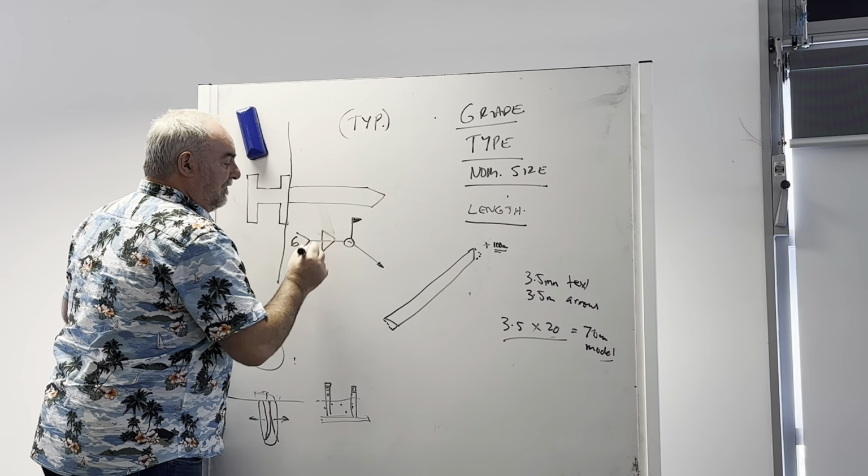Sorry, are we told what the size of the base plate is? No, you've got to make that up yourself. There's a couple of dimensions there which you'll have to abide by. I'm just worried about the minimum requirements for the bolt placements and the H beams. They're going to clash in that sort of format. So if you extend the base plate a bit this way and that way, then you might be able to get it to fit, in case our minimums don't fit with the alignment we've got.